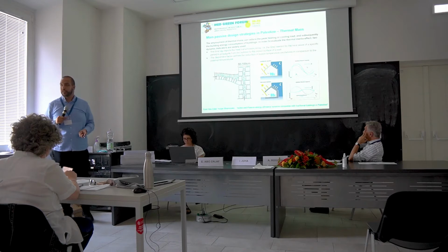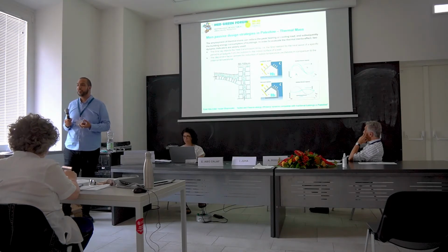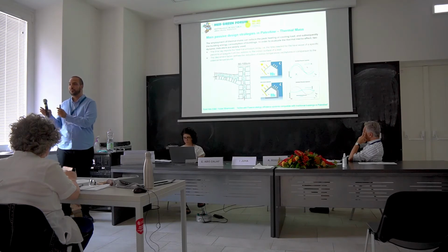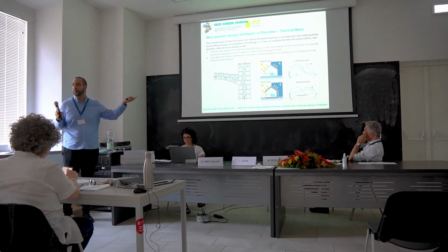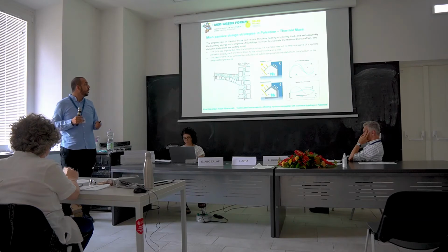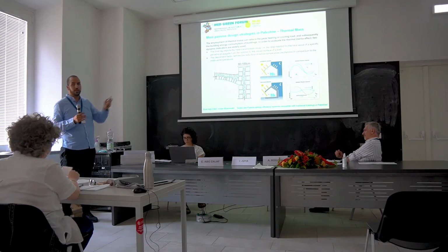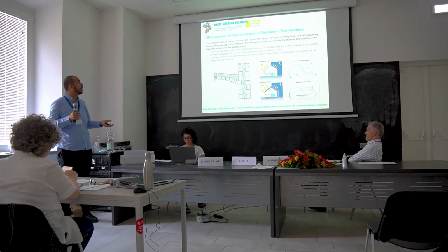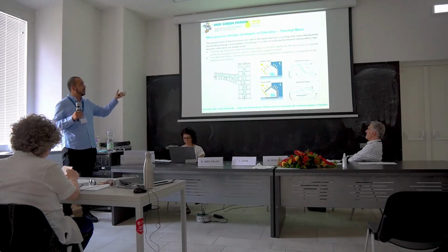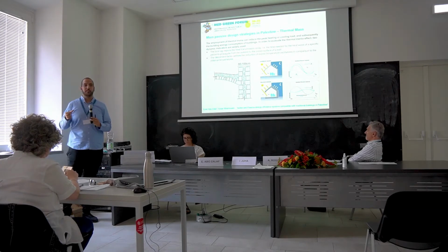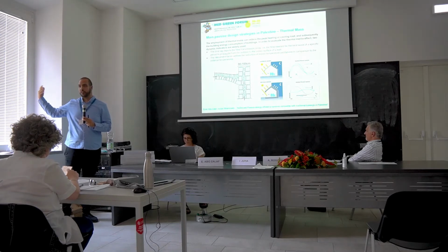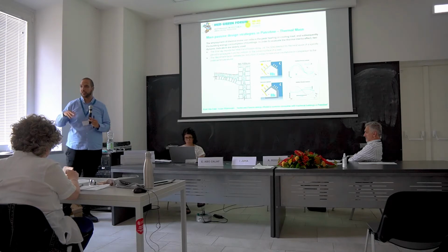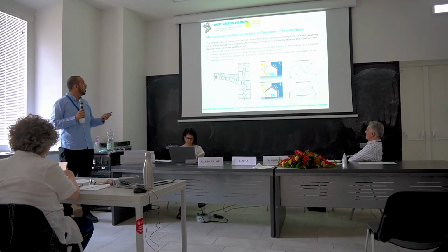Secondly, the thermal mass. Thermal mass in a heritage building is always there because the walls are 1 meter thick, or 80 centimeters at minimum. Because of the thickness of the wall and the material used, you always have thermal mass. We can explain it by the time the heat needs to travel from the outside of the building to the inside, and vice versa.